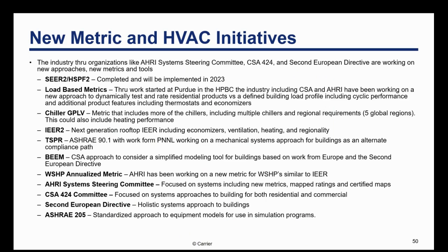So some of the new metrics that we're starting to work on. I mentioned SEER2 and HSPF2. There's interesting work underway at Purdue called load-based testing. It's really being pushed a lot by Canada, where we stick a unit in a room and we have a load profile that we feed into the data system that's a real building, and we track the residential unit from zero load to full load and look at cycling and all those sorts of things. We're also working on a new chiller metric that'll factor in regional requirements and multiple chillers. Working on an IER2 that'll probably include the economizer and the ventilation. It may actually go the load-based testing approach.